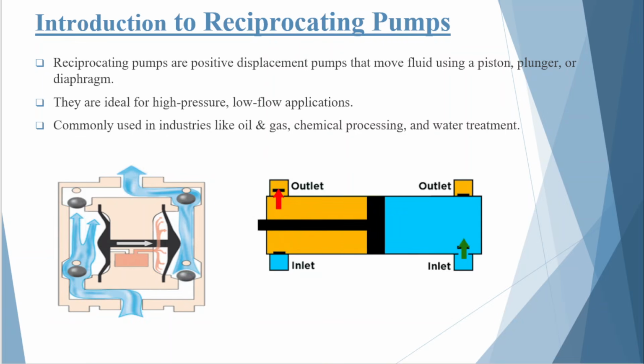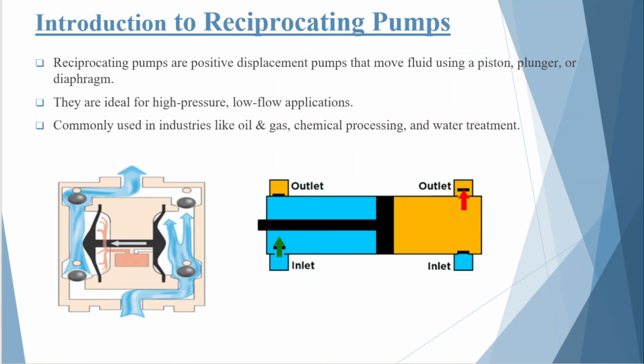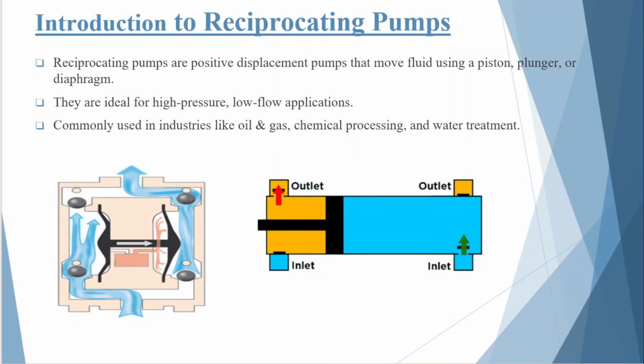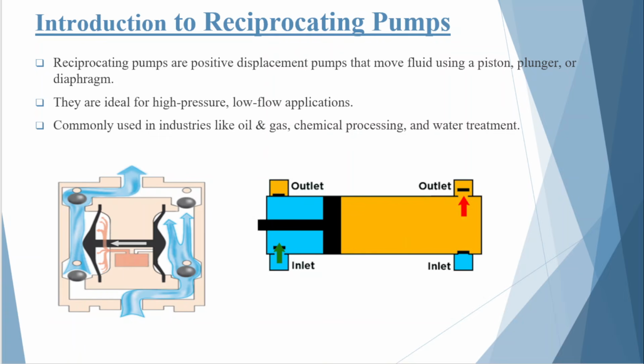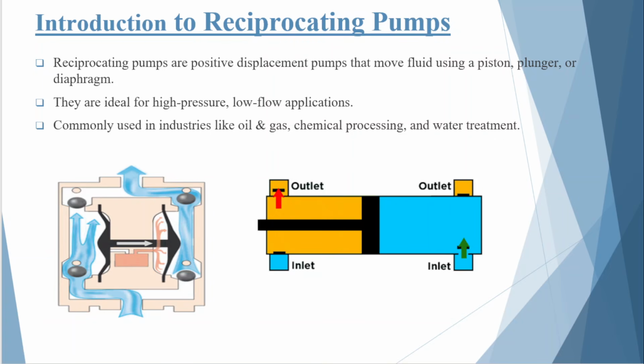However, because the piston continuously starts and stops during every revolution, the liquid inside the piping also accelerates and decelerates continuously. And that is exactly where the concept of acceleration head begins.